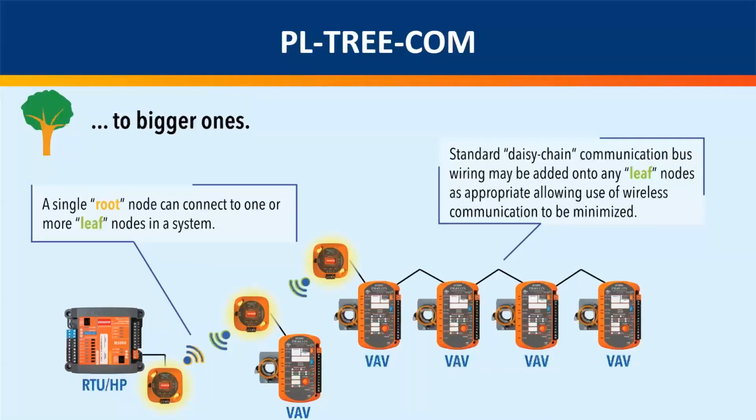Because we will already have that input designated as a humidity sensor, and that sensor, once it's physically into the controller, can go multiple different ways in the logic. So it's not like you have to choose, are you going to use that humidity sensor for dehumidification or for dual enthalpy control. Once it's in, it's available.